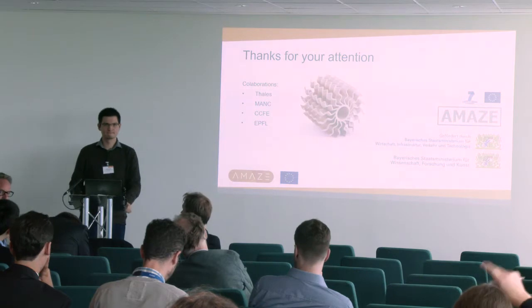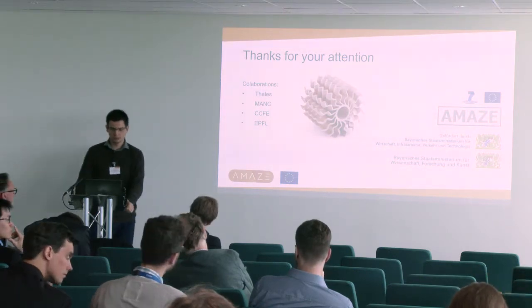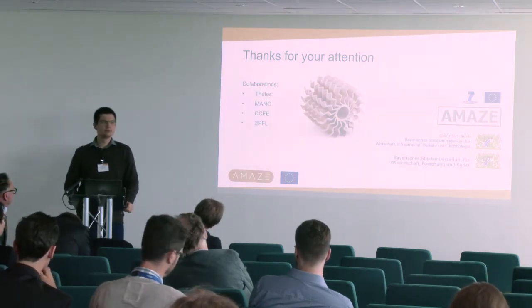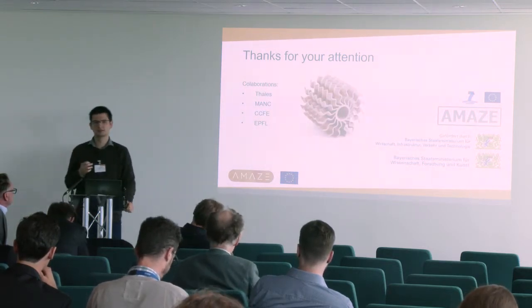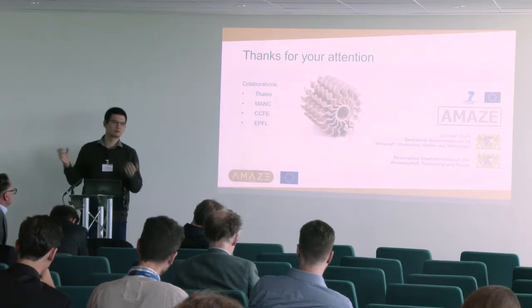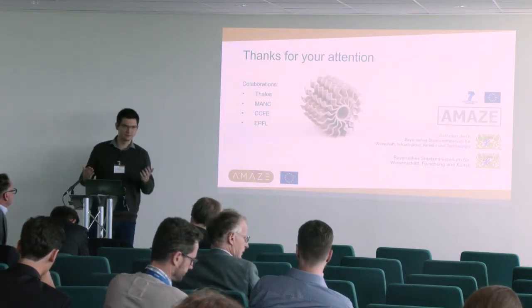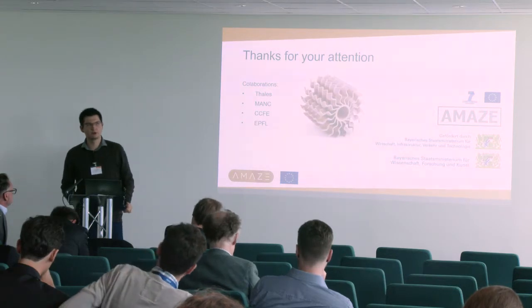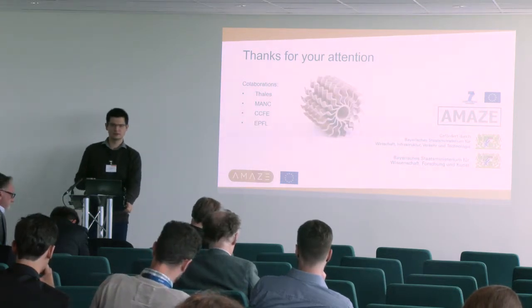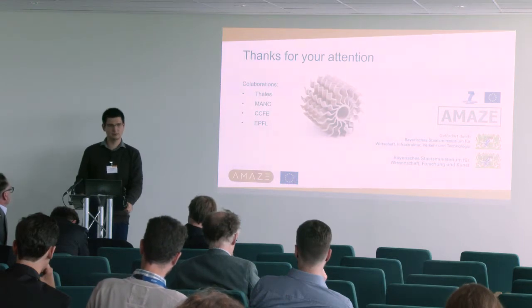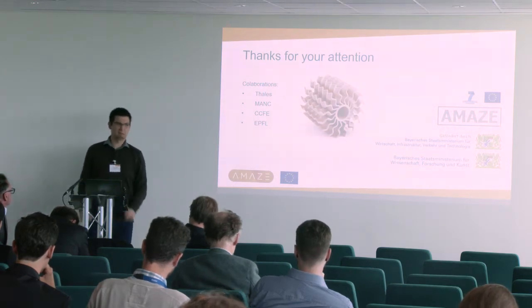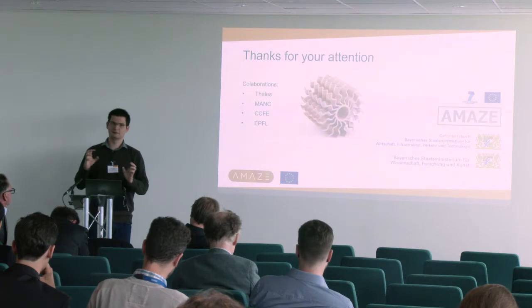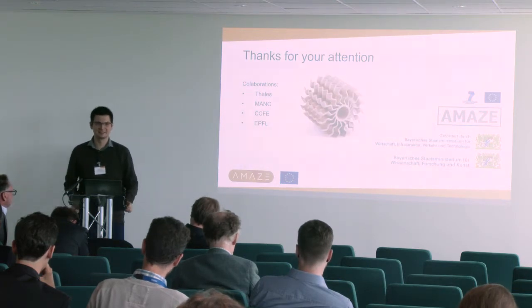Thank you. What cell size are the structures that you have? Right now, as I said, our beam is about 400 microns. So this is the electron beam problem that we have right now, we don't have better beams. We can build even smaller with the newest generation of Arcam machines, the Q10 and Q10T, going down to 100 microns, but that's about it. But if you build at 100 microns, there is a missing powder particle or a stuck powder particle. So that's the limit.